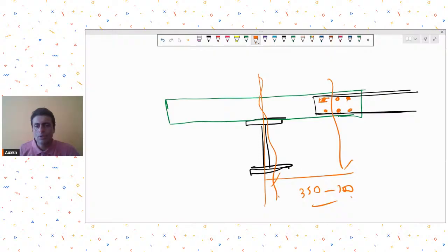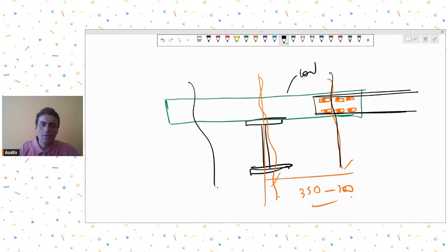So even though there are slots over here, because of the manner in which the continuity forces will act, it still provides effective continuity. Although I will also have to think more about how exactly these slots are designed and provided. But because of multiple slots that are provided, and it's not a single bolt hole with a single slot, it is still able to maintain its continuity.